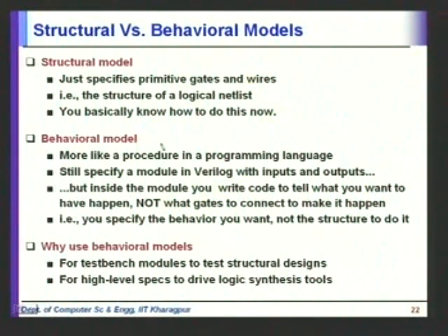The behavioral model is like a procedure in a programming language, and you still specify a module in Verilog with inputs and outputs, but inside the module you may not have gates and things like that. You can write code to tell what you want to happen. Okay, not what gates to connect to make it happen.